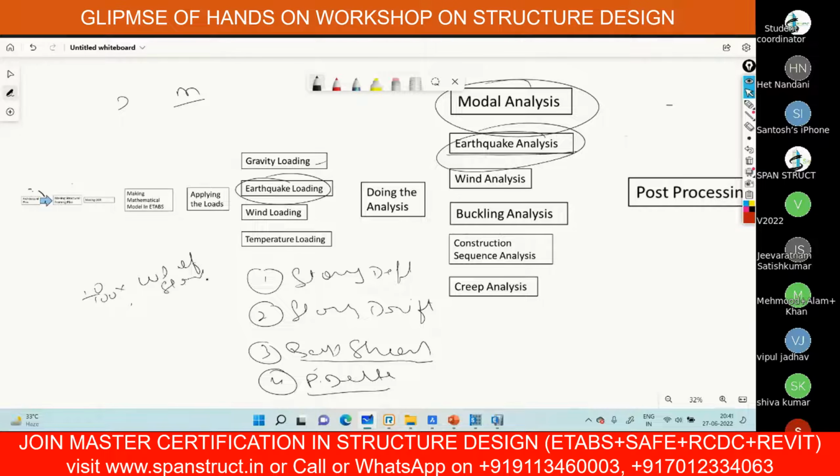So this much percentage of the weight of the structure you can apply at the maximum, and the minimum you can keep is 1 to 2%. So this information about applying the earthquake load on the structure, we will get from the earthquake analysis here. Okay, like the same, we have a wind analysis. In that also we have to keep what actually the maximum lateral deflection you're allowing.